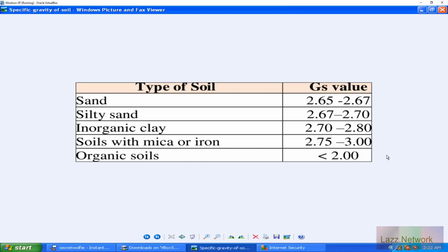Obviously, if you want to know your sands to any kind of ratio like that, you do a sieve analysis. You do a sieve analysis, and then obviously your lab person would note if they want to know specifically if there's what they like to call fibrous material. And usually fibrous material is considered organic material, like roots, twigs, wood chips, any kind of wood fragments. That's typically what we see when it comes to organic soils.